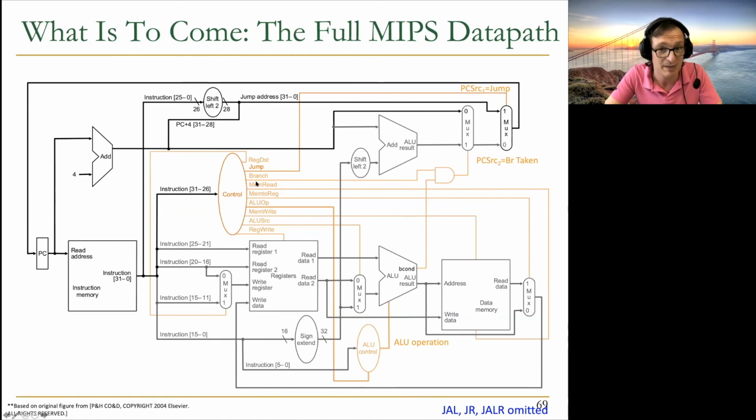You can see that. They control whether you're writing data to memory. There's mem read over here and then mem write over here, whether you're reading or writing from memory. They control whether the data you're writing to the register comes from the ALU output or memory. So you can see that there's a mem to reg signal. If this is set to 1, then the data that you're writing to the register file comes from the memory. Otherwise, it comes from the ALU. And we will see why these are important. So we're going to build a data path to enable this.